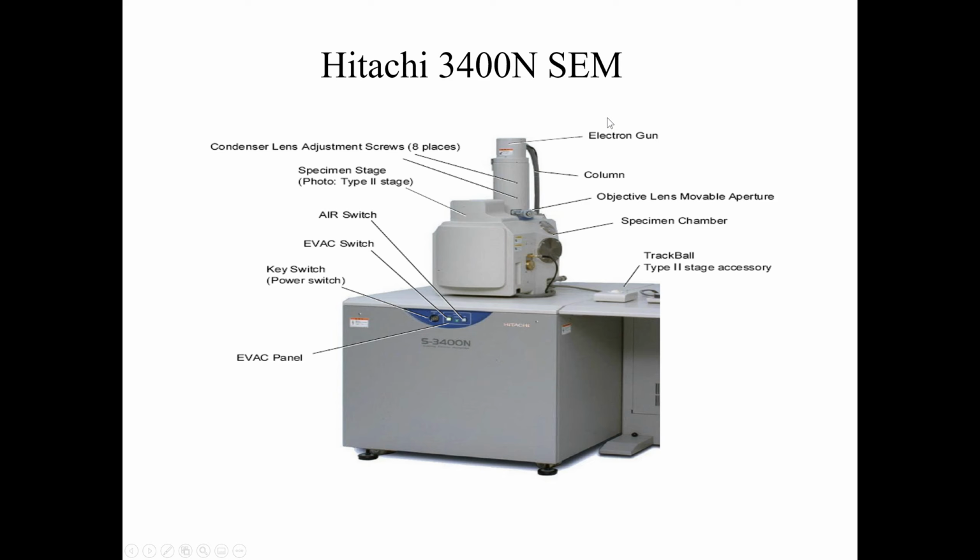But there are some private companies that actually have these in their own basements. They use them for asbestos monitoring and some stuff like that. So it is conceivable for a private citizen to buy one of these, because all you need to run it is 120 electric power. There's a 208 3-phase that goes into it, but there's no water requirements. There's no water chiller. There's no fancy radiation shielding. All you need is basically a breaker box and a dedicated line. The 120 wall current is for the vacuum pumps, but the 208 3-phase is for running the microscope. Voltages at people's homes are 220, 240 volts, so it's no big deal.